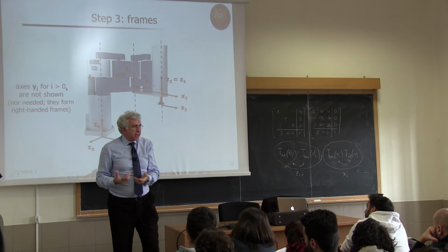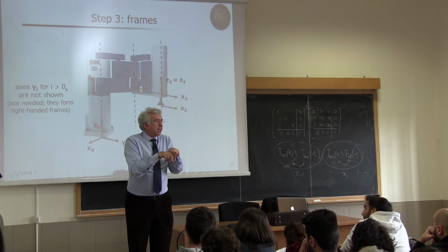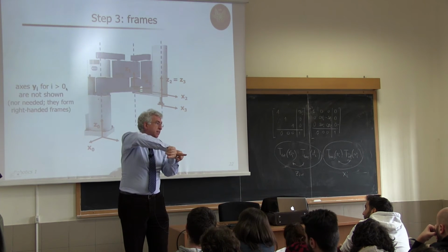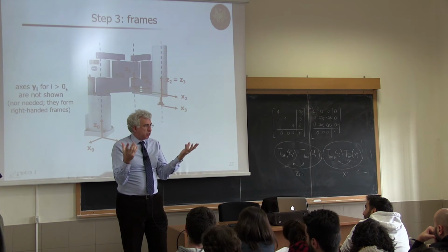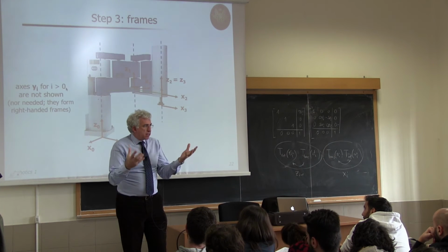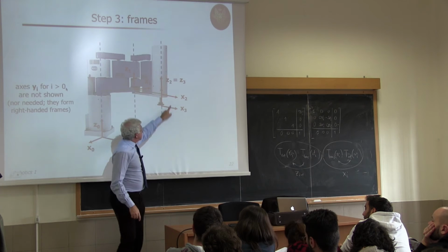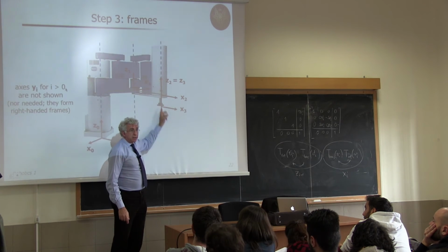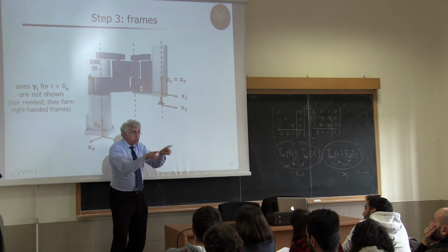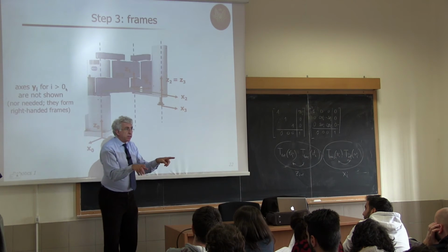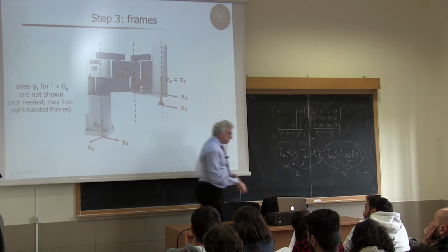Then I have to compute sine and cosine of this angle, while I can zero it or put it at 90 degrees. I mean, these are the standard choices. It's arbitrary, but I choose the most convenient one, 0. So I align x3 with x2 because this is a prismatic joint, so there will be no change of theta in moving this joint. Okay?